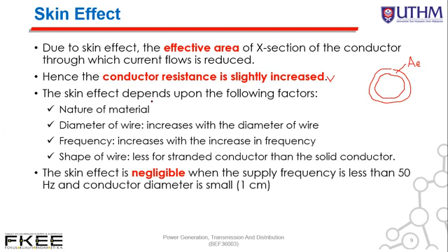The skin effect depends upon the following factors: the nature of the material, the diameter of the wire, where increasing diameter will increase the skin effect, the frequency, where an increase in frequency will also increase the skin effect, and finally the shape of the wire.